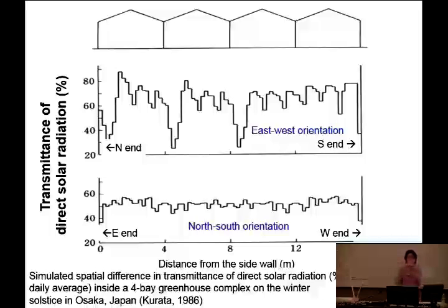All right, in east-west orientation, usually you have an angled roof, right? I don't have a small greenhouse model, but usually it is like that. That means there is a high chance to get a very small incident angle. So that's why the transmission is high. So you have pros and cons. Growers need to make the decision: do I want to give high priority to uniformity, or no, because my plants are actually moving in a greenhouse?